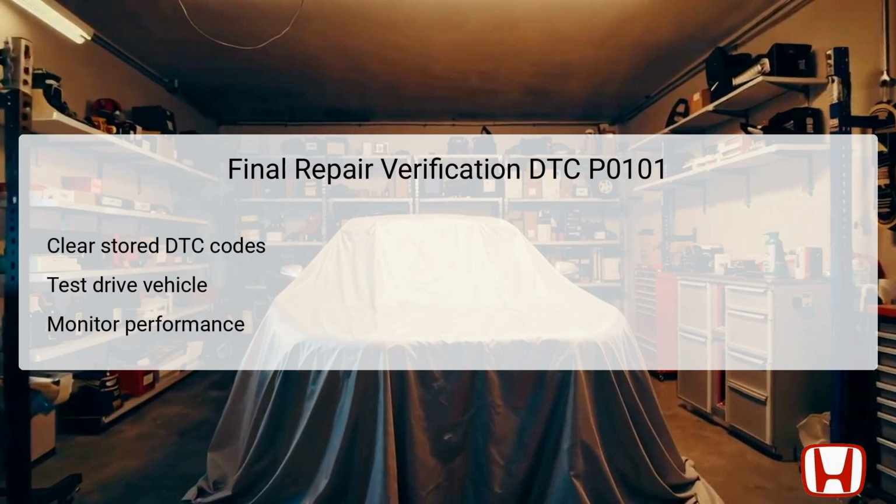Following troubleshooting and potential repairs, the final verification step involves clearing any stored diagnostic trouble codes, DTCs, from the vehicle's PCM. Once the DTCs have been cleared, it's crucial to conduct a test drive under various conditions to observe the vehicle's performance. During this test drive, monitor for signs of the original issue reoccurring, such as engine hesitation or reduced performance. Keep an eye on the check engine light, ensuring it remains off throughout the test drive.